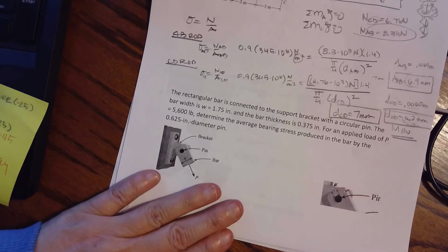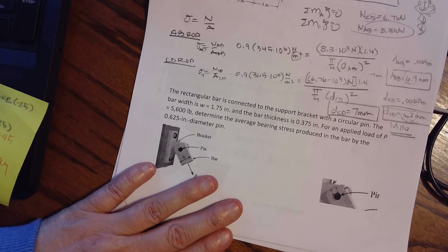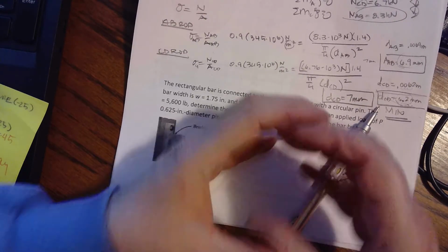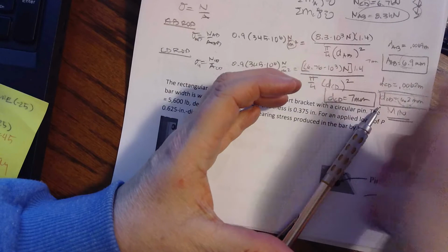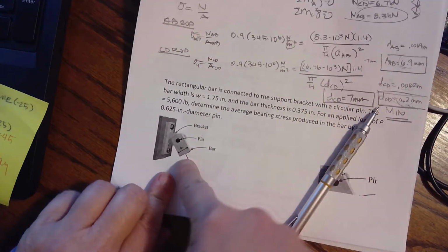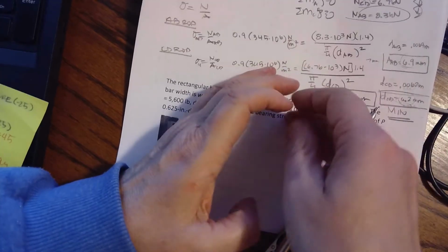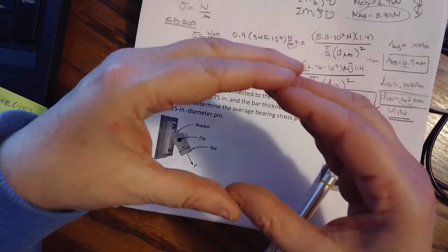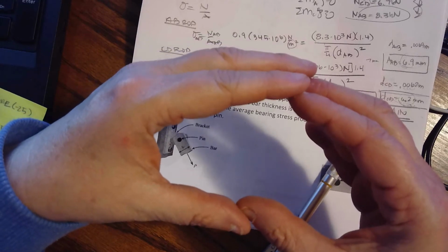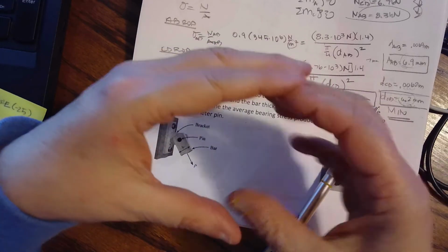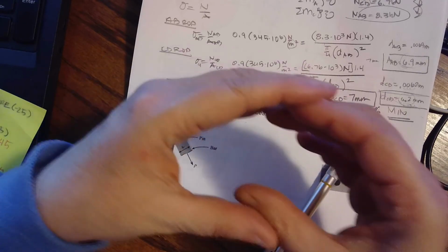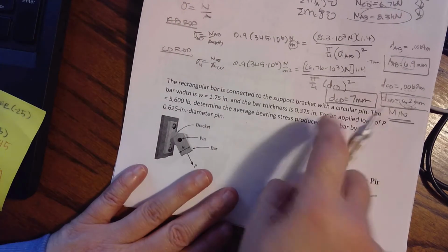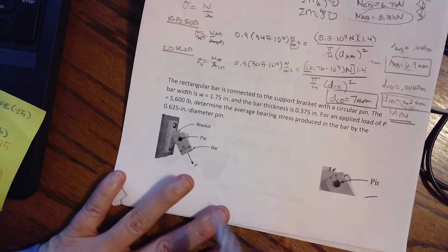Okay, so this one is a bearing stress by the pin on the back of a hole. So if you have a hole and you have it fitted with a bolt, and you end up pulling on this metal bar like that, depending on the materials and the load, you could end up skewing that hole. And you guys have all seen holes that have ended up skewed, and they're no longer round. They're harder to get the bolts in and out of, but you could also end up with play in this connection that you are not counting on. Okay, and so let's calculate then that bearing stress.